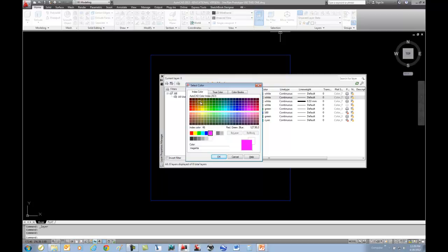And then up here, they may reserve this for illustrative maps that would actually use color to print. So these 1 through 9 might print black ink only and not in color, where the bottom grays would print in grayscale, and the ones up here, colors 10 through 249, would print actually in color. So you could have a combination of results. Here, for colors 1 through 9, we're going to use magenta. That's a bold color, bolder than red and yellow for sure, based on our civil plot style.